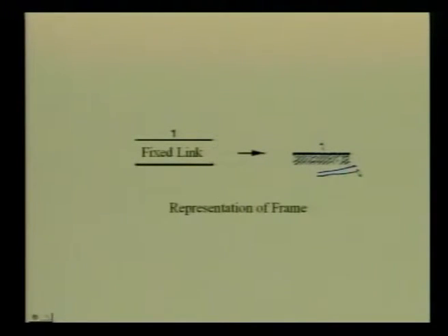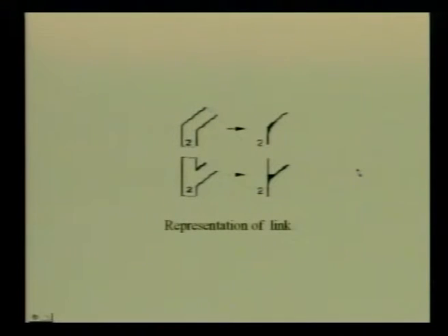All the numbers are linked sequentially starting from 1. This diagram shows that even if the link has some width or some height, which are completely irrelevant so far as the kinematics is concerned. So, in the skeleton diagram we represent these links, say number 2, by a line drawing. This link having such a bifurcation will be represented like this line drawing.